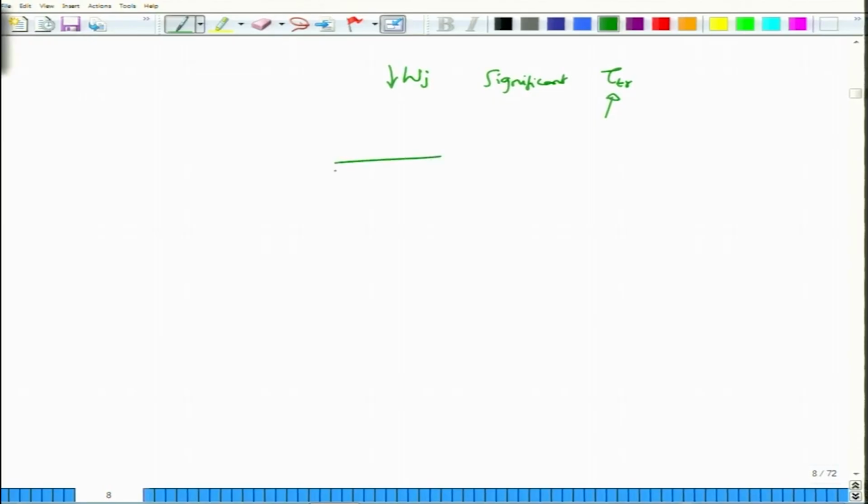But when you make Wj very short, there is also an additional advantage. Decreasing Wj means that a lesser value of V bias is required. So, you do not have to apply bias voltages of 50-60 volts, you can apply bias voltages of 5 to 10 volts, and that reduces the static power consumption, or rather the voltage requirements, of these devices.